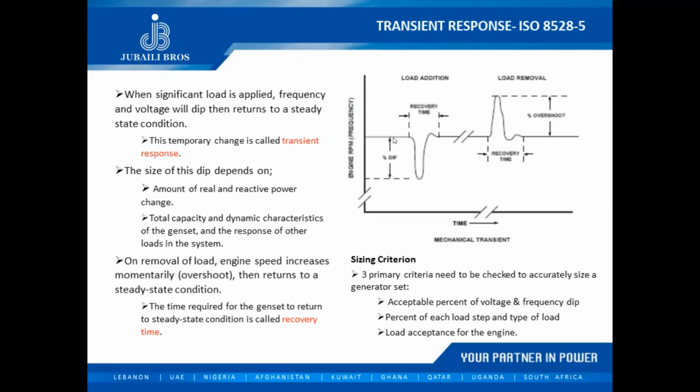Our frequency would dip. Okay. We suddenly apply a load, our frequency would dip. This is similar to driving a car with cruise control. My cruise control is set at 100 kilometers per hour. Suddenly I go uphill, okay? My speed would decrease slightly, then it would recover. So same thing happens here. My frequency would dip, my governor will pump in more fuel, my engine will regain its speed, and my frequency will recover. Okay, same happens.